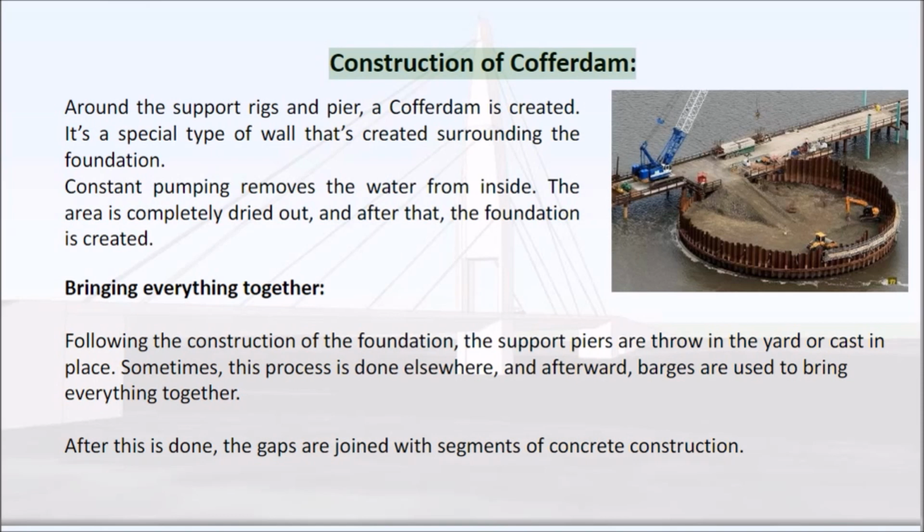Construction of cofferdam. Around the support rigs and pier, a cofferdam is created. It's a special type of wall that's created surrounding the foundation. Constant pumping removes the water from inside. The area is completely dried out, and after that, the foundation is created.